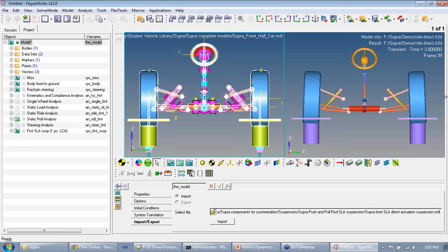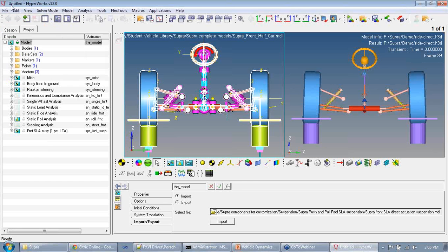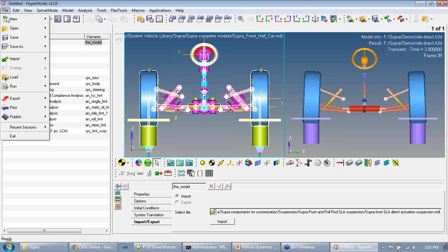There is one more thing that we have that might be useful to know. Sometimes what you want to do is plot a whole bunch of results so that you can compare different simulations together, and at the same time see as many of the plots to compare as possible. For that we have created something called the HyperGraph templates, and I'm going to show you quickly how to use them. They're a really useful and powerful thing.